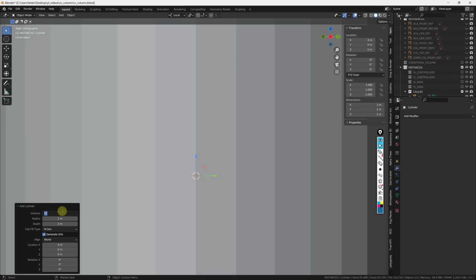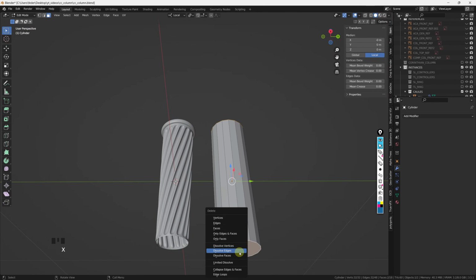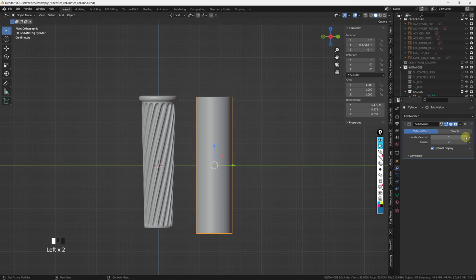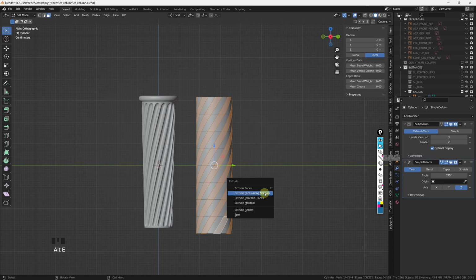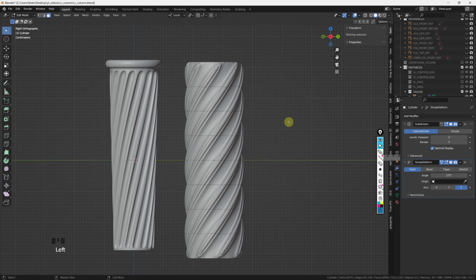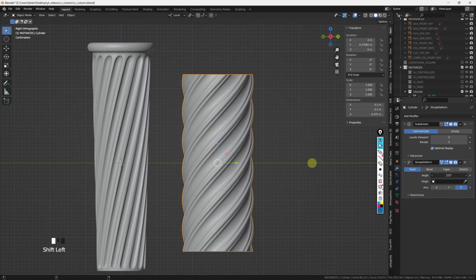This very same technique can be used to create apparently complex structures. Provided that you have enough horizontal geometry, you will just need a subdivision modifier and a simple deform modifier set on twist on the z-axis. You can then experiment by selecting face loops and playing around with the extrude and inset operations. And this is the technique I would use in order to model some Gothic columns you may see in different cathedrals, but this is of course for another story.